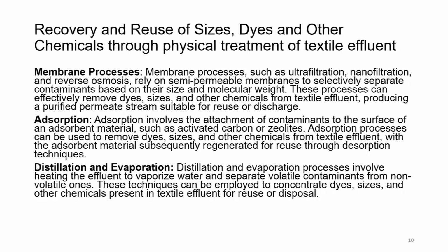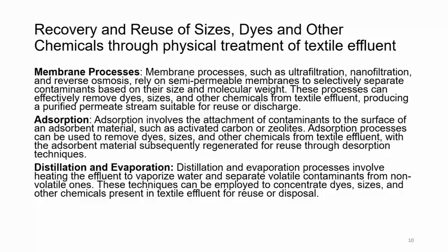So, even distillation and evaporation type of processes can be carried out to reduce the water volume by vaporization of water and separate the volatile contaminants from non-volatile ones.